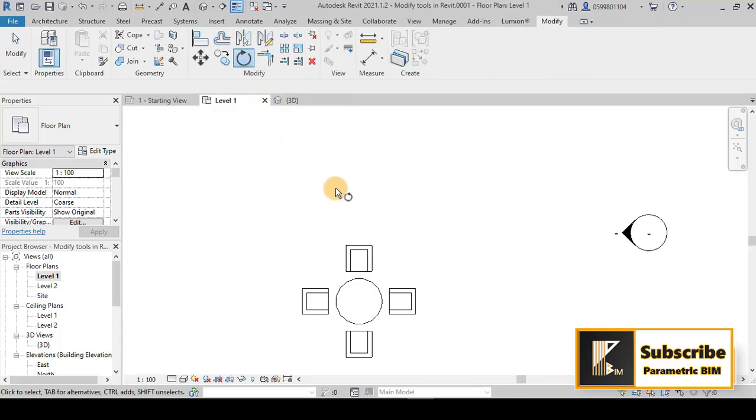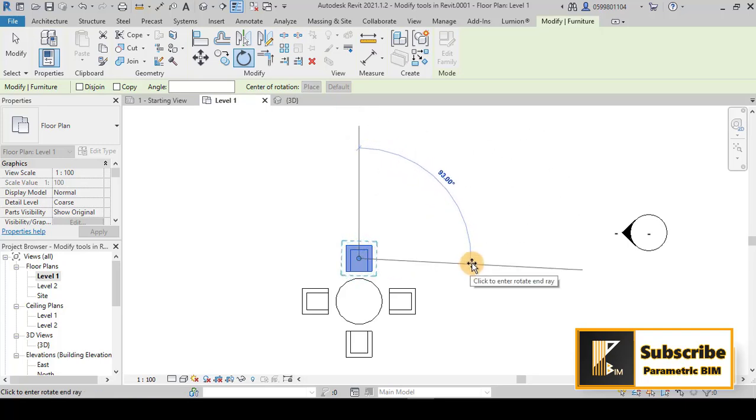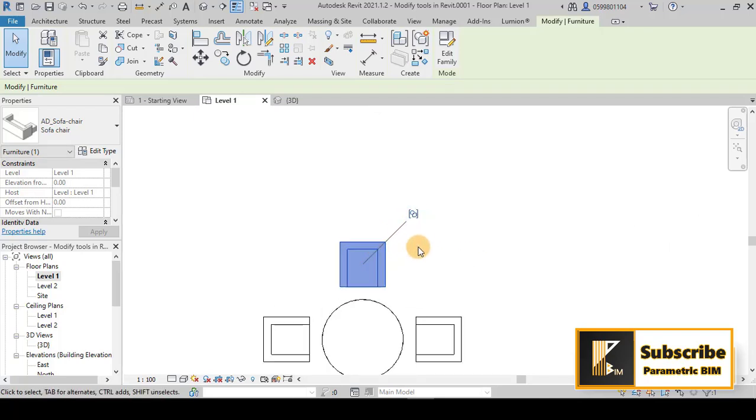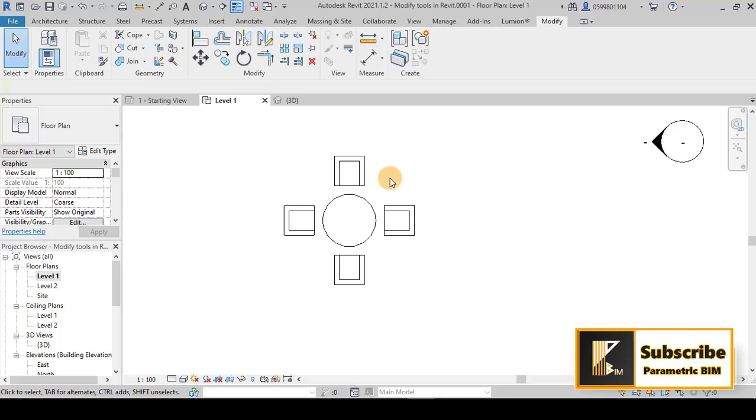I will select rotate, choose the object that I want to rotate, click enter, and as you see I have now the flexible line, but I have to click from where to start rotating this object. So if I want to rotate it 90 degrees, for example, it will be rotated like that, but it is not rotated here because it is now in a group of array, so this will not work.